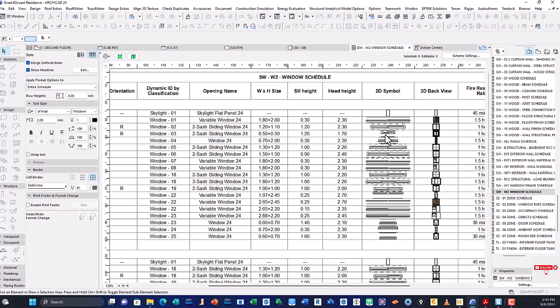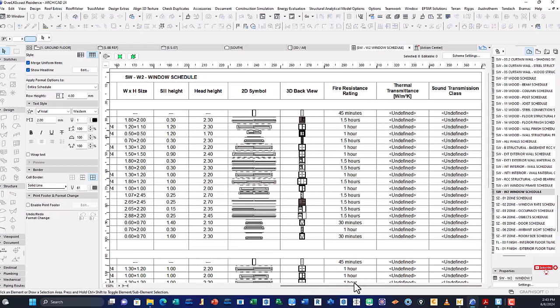As you're watching this video, if you glance back over what we were coming from, you'll find that this symbol is identical to the one on the ground floor. So this is our window. We have a 0.5 by 0.5. It is window 3. After ArchiCAD has updated the window schedule, I'm now free to open any schedule that has the element window attached to it.